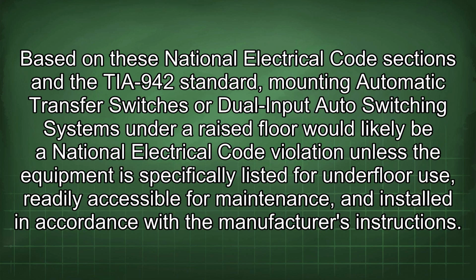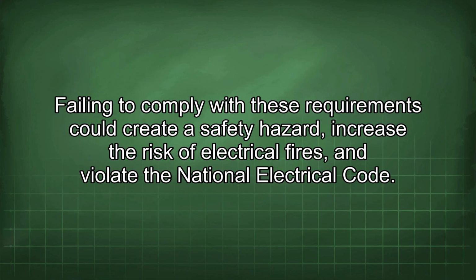Based on these National Electrical Code sections and the TIA-942 standard, mounting automatic transfer switches or dual input auto switching systems under a raised floor would likely be a National Electrical Code violation unless the equipment is specifically listed for underfloor use, readily accessible for maintenance, and installed in accordance with the manufacturer's instructions. Failing to comply with these requirements could create a safety hazard, increase the risk of electrical fires, and violate the National Electrical Code.